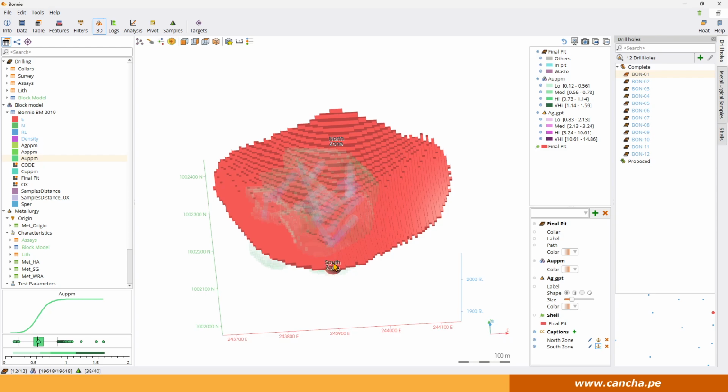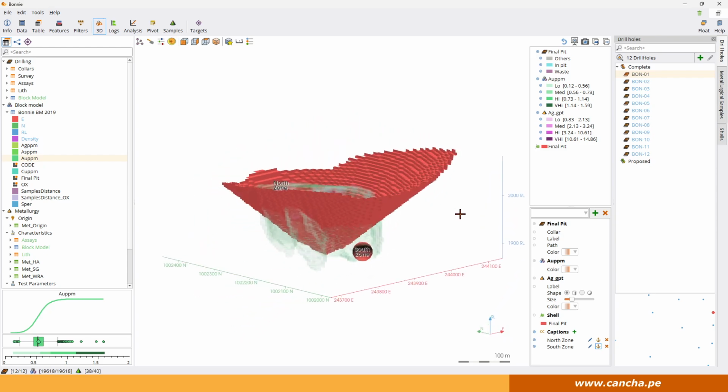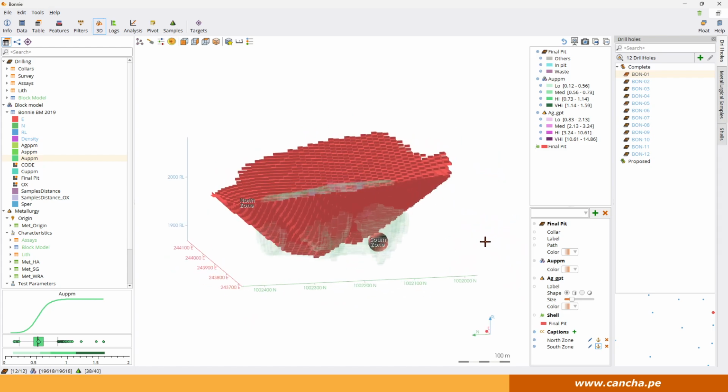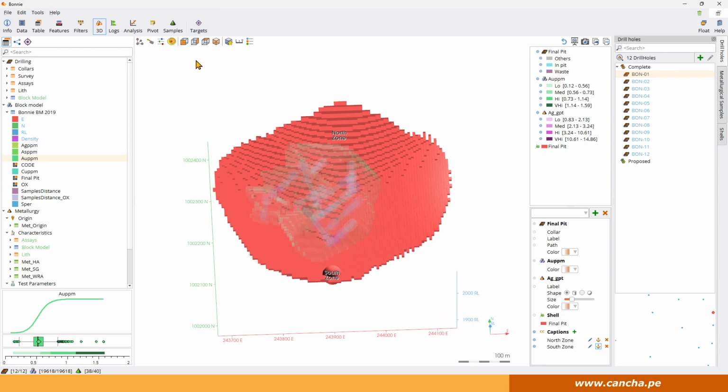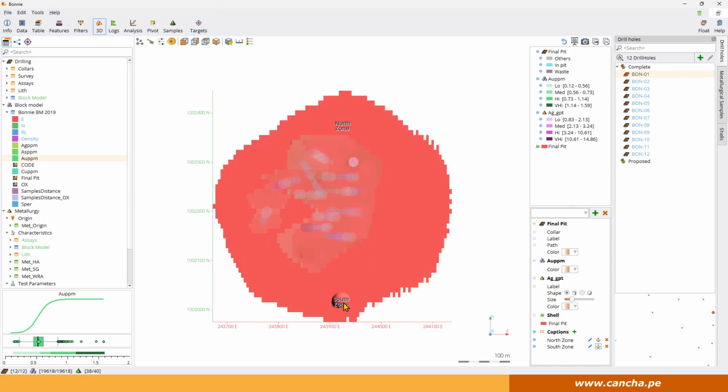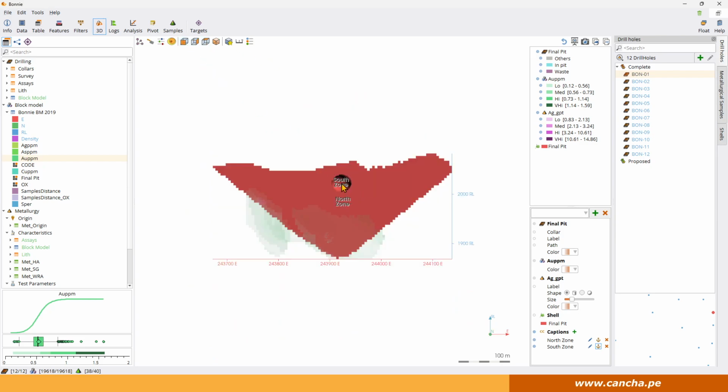Pull it to the south. Now you'll notice I'm pulling it on an angle right now, so I've actually pulled it down. Okay, so you just have to pull it back up again. This is why it's better to use these projection ones, because if you're using the projection one, you can have them just on the same plane. Are they both the same height? No, they're a bit different. Let's put them both the same height, and take it out of anchor mode.